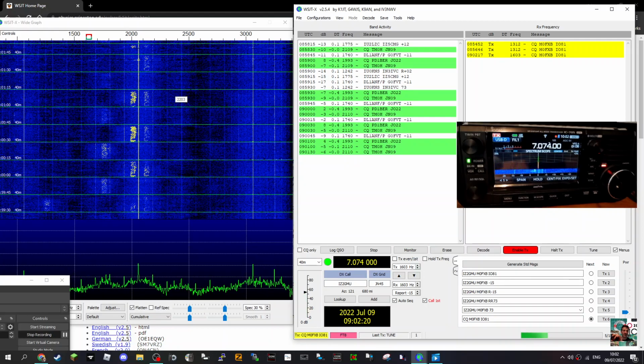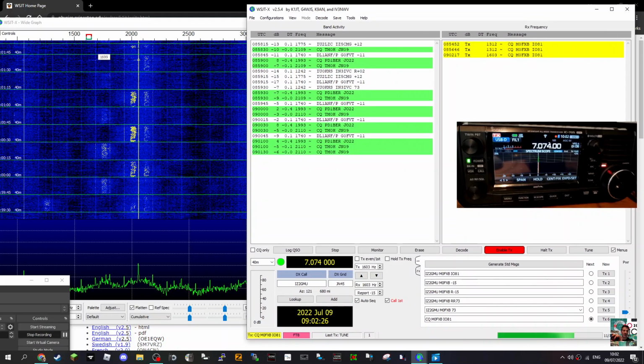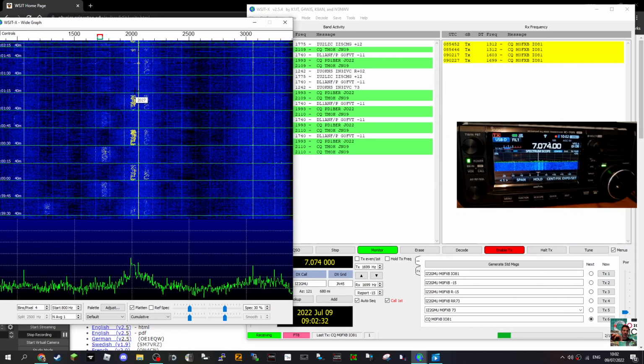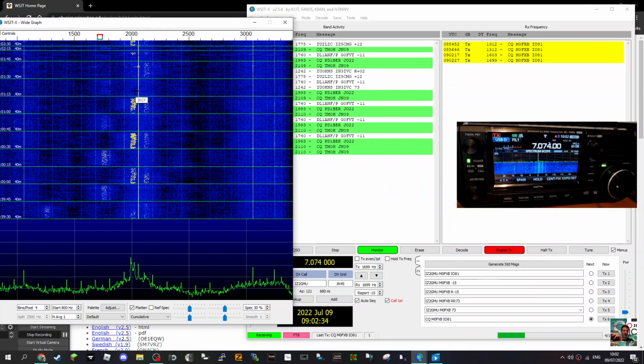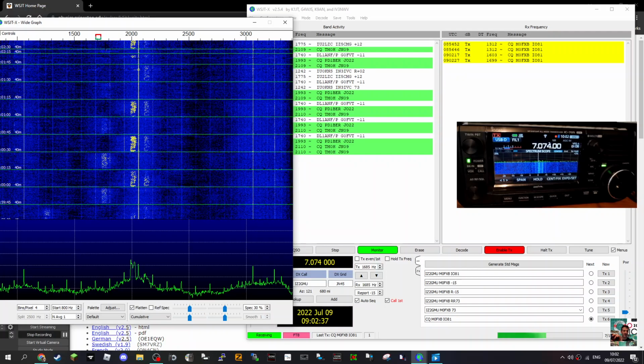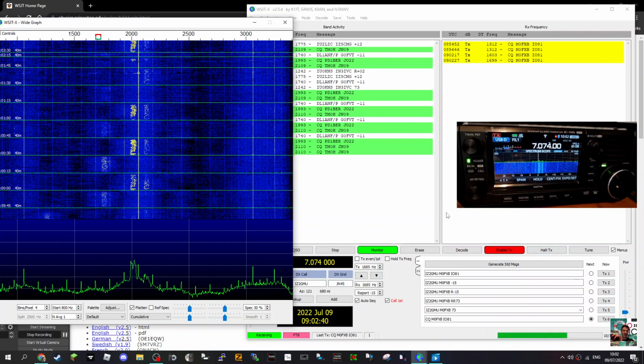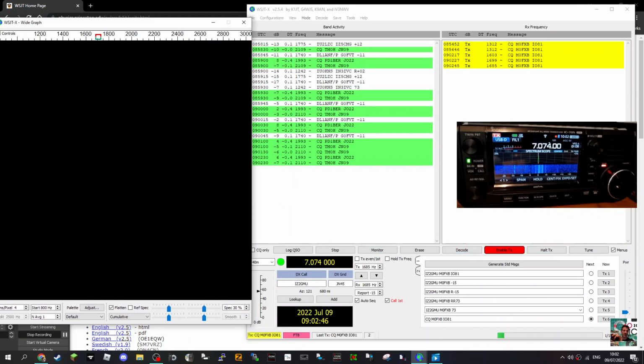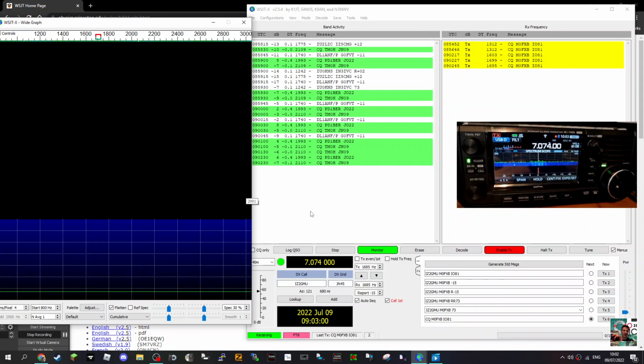And then look to get it auto TX, and you just Enable TX, and it's now TXing. What you can do here with the big blue graph here, just right click where there's a space, and normally this will be full of yellow things coming down. It's just my antenna's a bit rubbish today, and so look for a gap, set Rx TX, Enable TX. It's going to start TXing automatically now, as you can see. Just move that across. So it's gone black because I've moved it across and it's in TX. If you look at the 705, you can actually see on the screen that it's TX, and you can see the signal on the scope. Just keep an eye on it, but it will do that automatically.